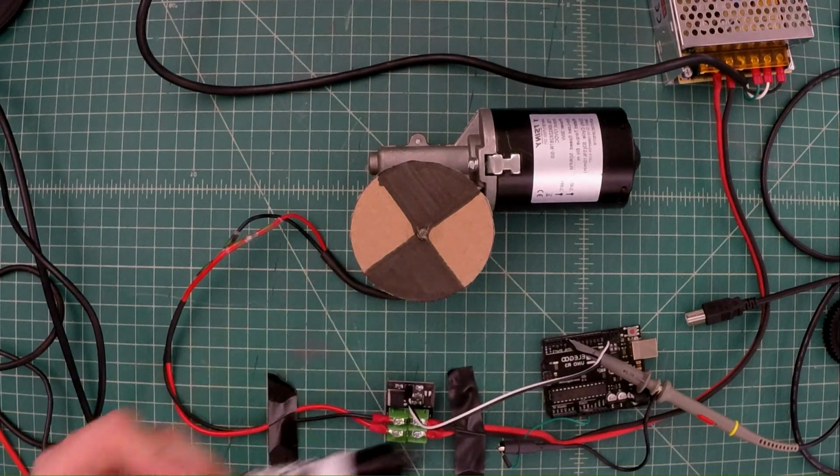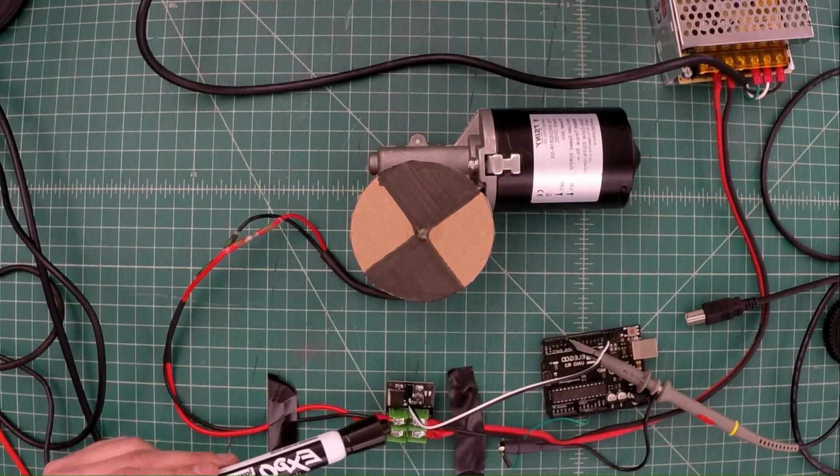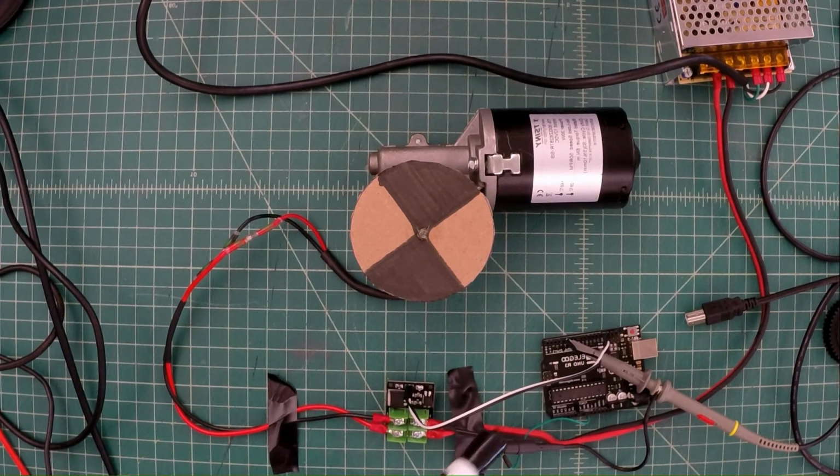So one of those is a ground connection, and the other one is connected to one of our PWM pins on the Arduino. Now, also connected to the Arduino over here is our oscilloscope. Okay, so the oscilloscope is an instrument which will measure our voltage as a function of time, and it can respond very quickly, so we'll be able to see that pulse width modulation signal coming to the transistor.